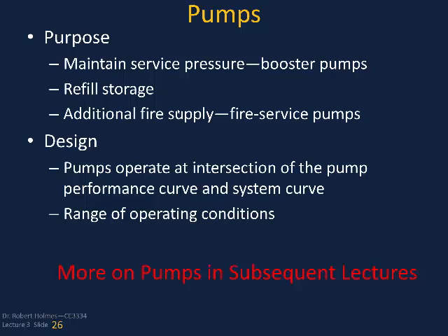In terms of designing them, we're going to talk a lot about this pump performance curve or pump head curve that's supplied to you by the vendor. The intersection of that and your system curve is something that you as the engineer, based on the system you're designing for, have to build. Where these intersect is where the flow rate is going to be for that particular pump. We'll talk a lot about that in the coming lectures. And then you're going to have various operating conditions, various flow rates you're going to have to worry about, so we'll talk a little bit about the range of flow conditions that you would have.